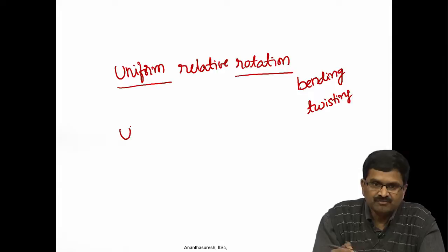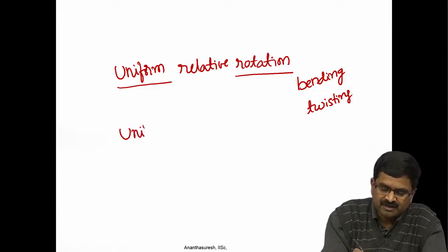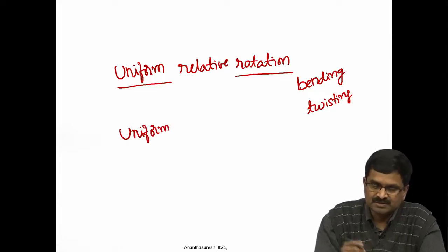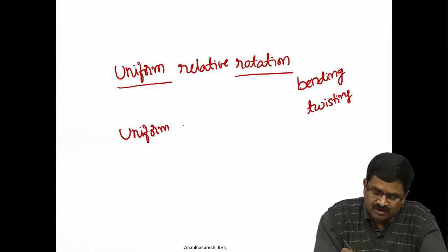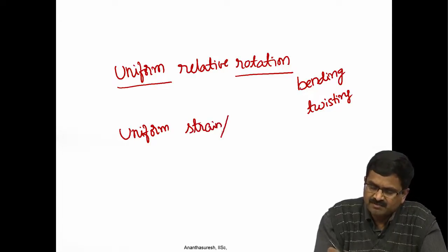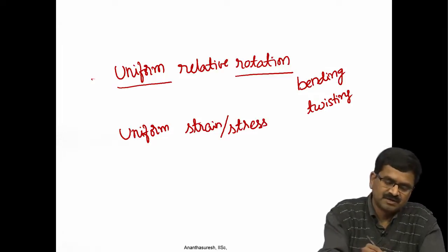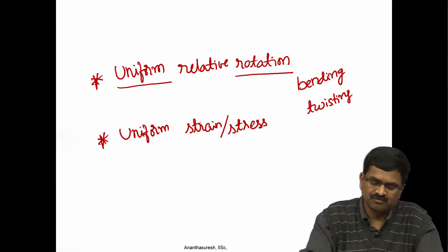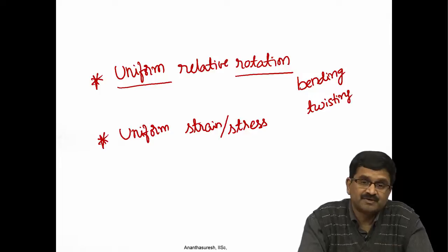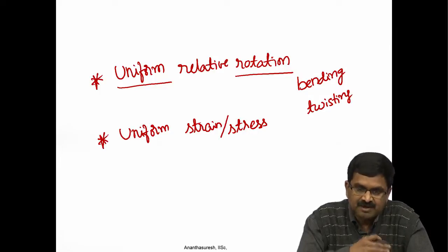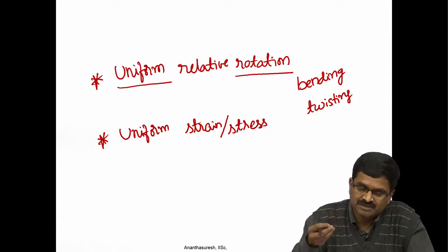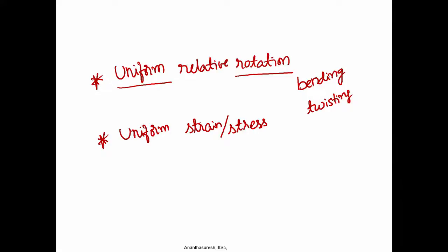Since this is not enough or difficult to implement with any formulation, although it has been done in two papers that I described today, we also want to have uniform strain. At the same time, it would mean that we will have uniform stress also. This is one characteristic, this other characteristic, uniform strain or stress. If we have that, that is actually very good, but compliant mechanism unlike structures cannot live with only uniform stress, because it has to have functionality. So there is disparity in terms of some regions being more stressed compared to other regions.